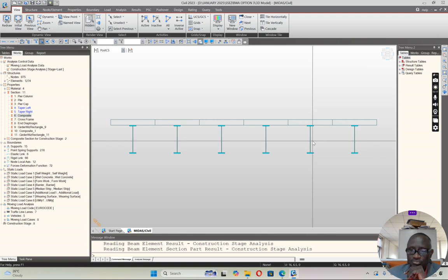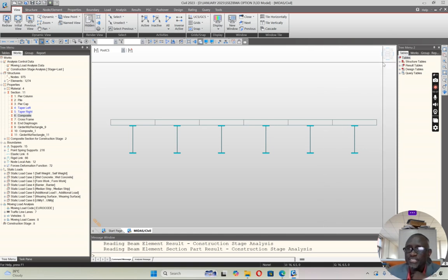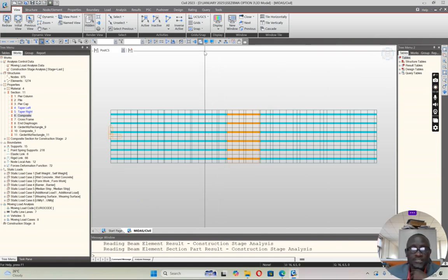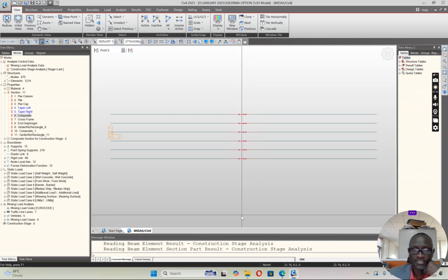You see the slab and you see the steel girder. You can't see the shear connector, but it will appear when you start design. It will appear in your output, and you will see how beautiful the shear studs are. So now we know where. I'm interested in the bending area, the shear area, and the hogging area. So I can pick this area. I highlight along the shear, and then the bending where I expect a lot of stresses to happen.